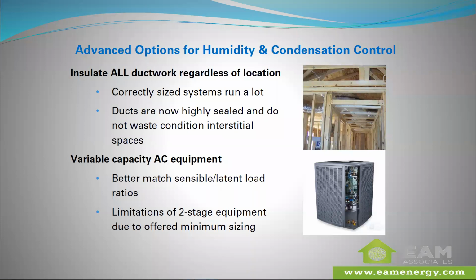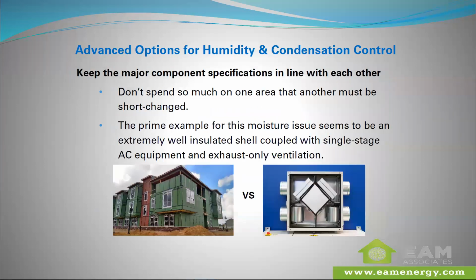And the problem that many of us run into is that as we're doing apartments and smaller homes, or even if it's a multi-zoned home and each individual zone needs that nice small piece of equipment, you just can't get it. That 1.5 ton unit is already way too oversized. So consider that.